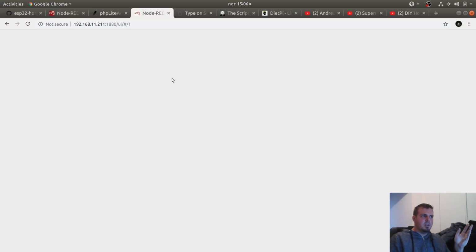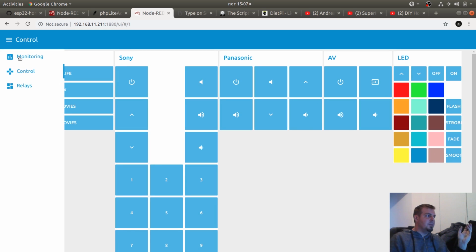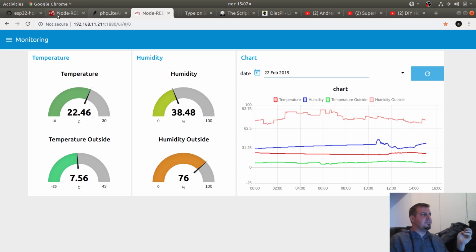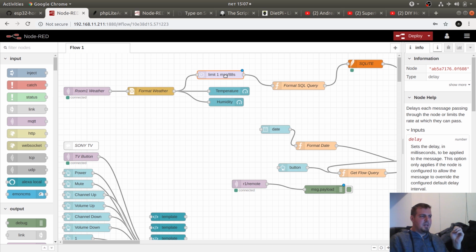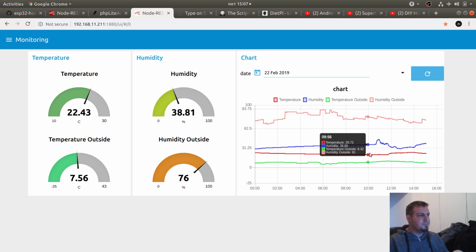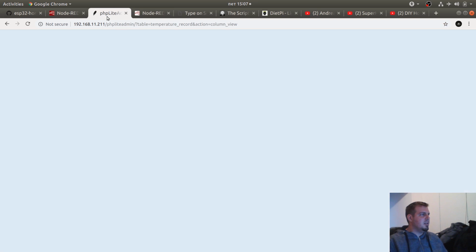I merely want to have a real-time update of the temperature and humidity in NodeRed, but I don't want to actually save it to the database. So that's why I limit to one message for 88 seconds, and that comes out to roughly 950 saves to the database a day, because the chart can only hold, I think, 1000 data points in one go. So that's why I'm saving one in every 88 seconds.